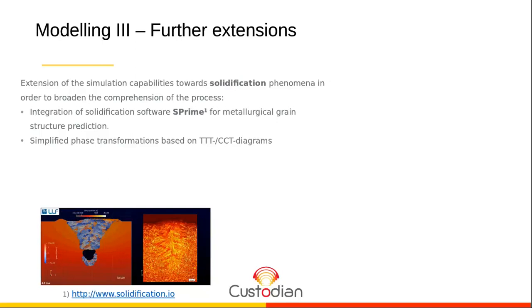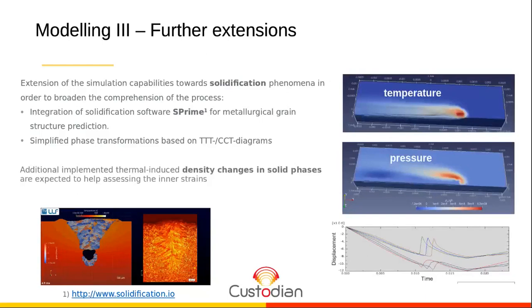And as Mauricio mentioned before, knowing the grain structure, you already have one part of the way walked. Something which is a novel approach from us in order to be able to assess not only the thermal fields but also the coupled effect of thermal fields and thermal induced mechanical strains is variable density solid phases.